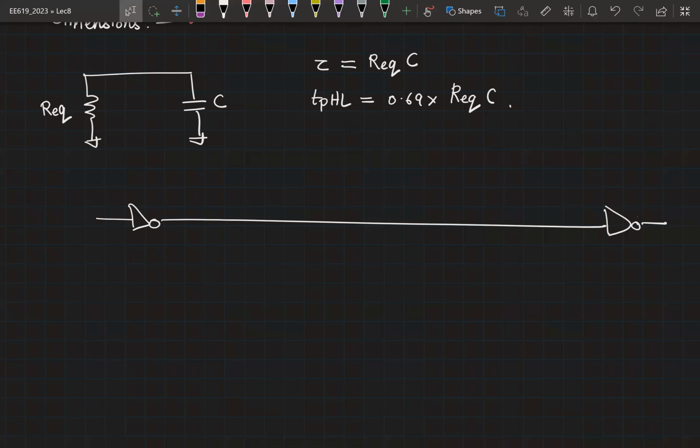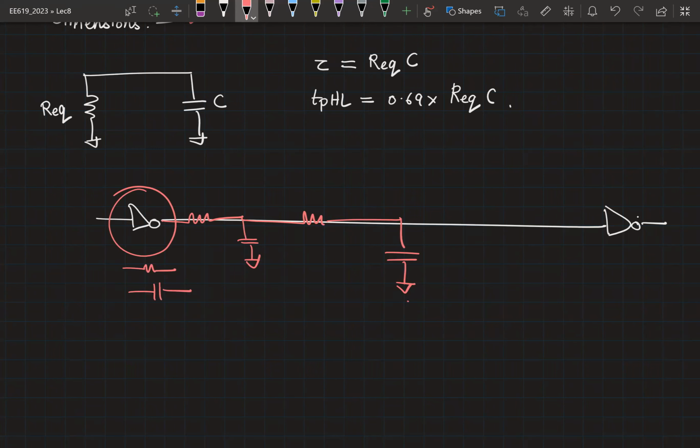So what that means is you will see some resistance, some capacitance to ground, more resistance, etc. Now, if you can simplify this circuit also in terms of R and C, the whole thing again boils down into an RC network. Right? So you have a higher order RC network, and we'll now learn techniques how to calculate delay in a higher order RC network. But the idea is we can simplify the whole thing into an RC network, and then you just have to deal with R and C in calculating the delay.